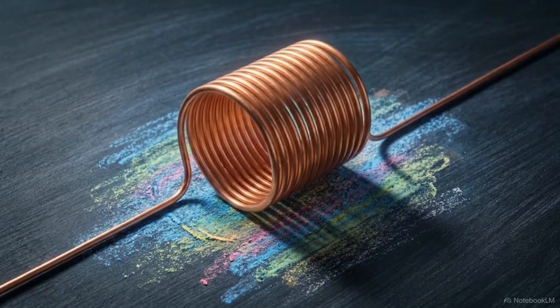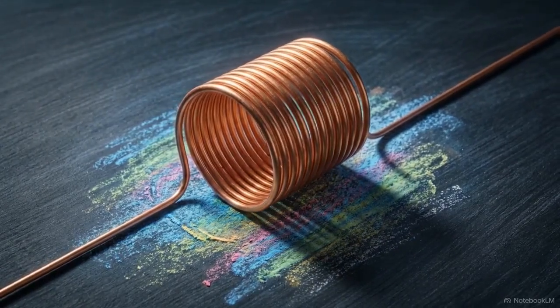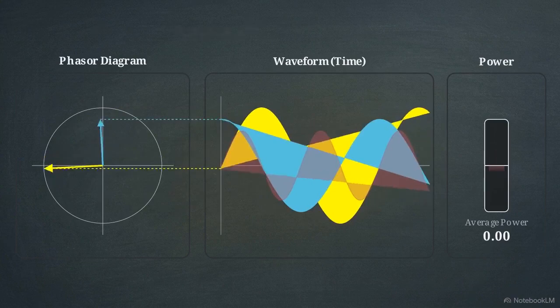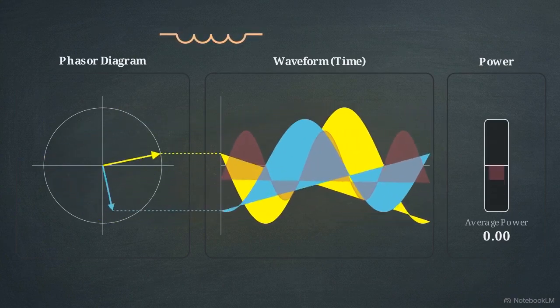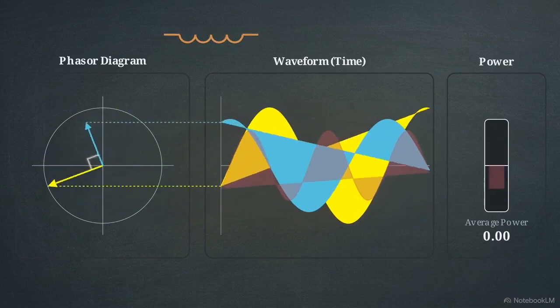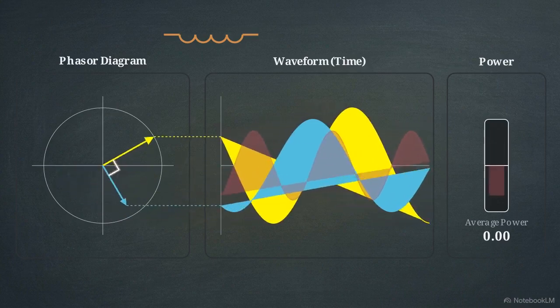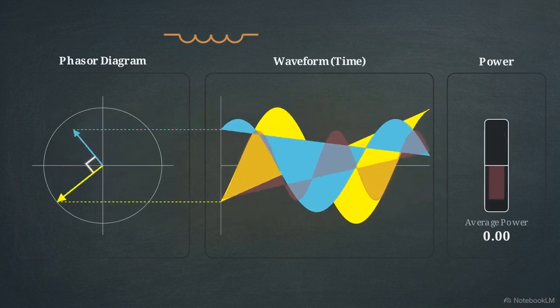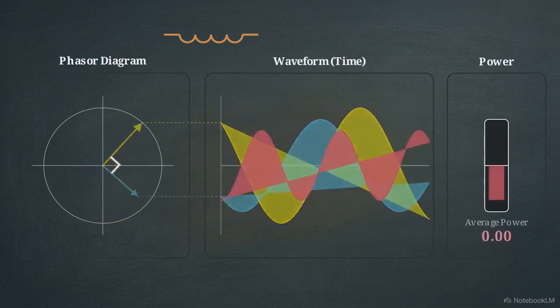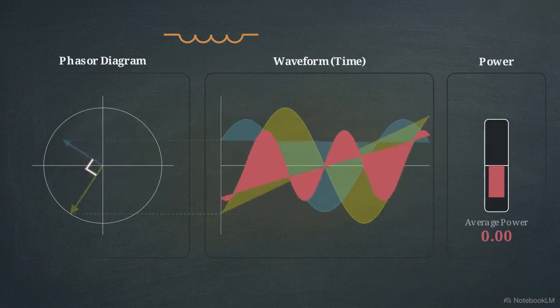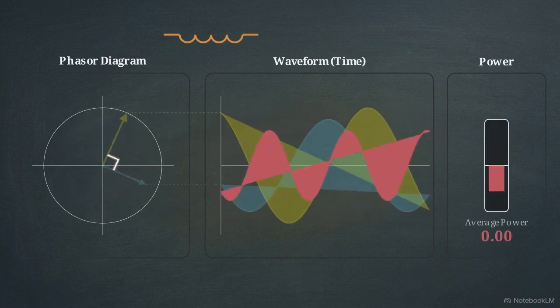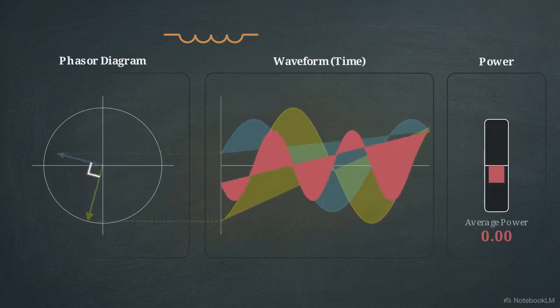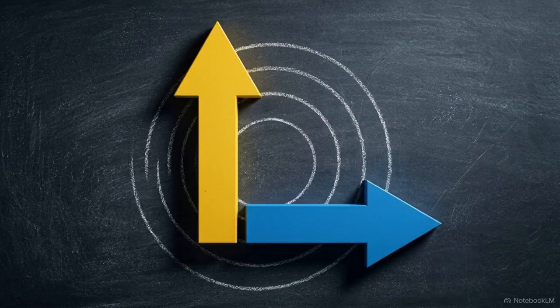Bringing these models together, the theoretical framework locks into place. Physically, an inductor inherently resists current changes. Mathematically, this forces current to lag voltage by exactly 90 degrees. Consequently, this specific delay forces power to oscillate perfectly, creating a zero net sum. This flow without consumption is a direct result of perfect geometric phase alignment.